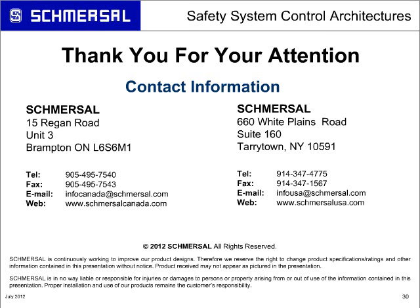Your presentation only mentions control categories. Do you mean PL levels or SIL? I thought control categories were no longer used. That's a common misconception from when the new standard ISO 13849 came about. ISO 13849 replaced the European standard EN 954.